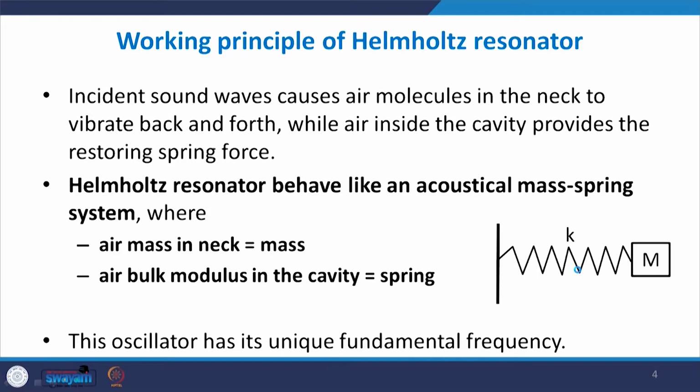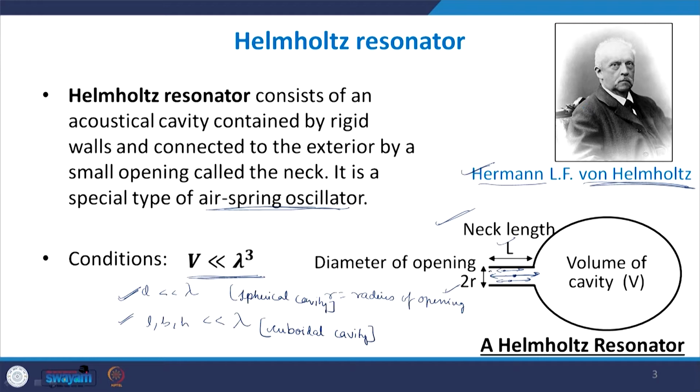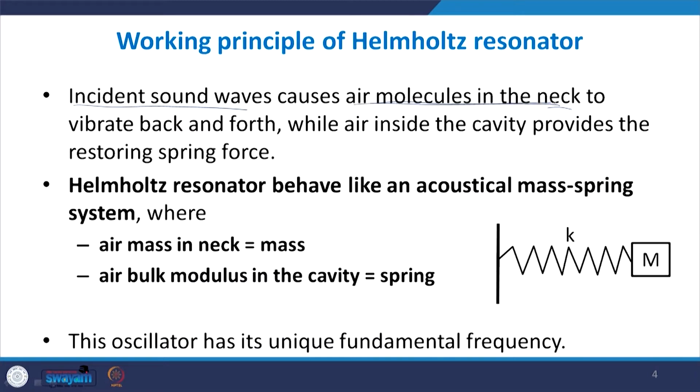So, the incident sound energy is driving these air molecules, and hence a heavy absorption will take place, lots of energy will be lost. That is what I have explained to you, that whatever the incident sound waves are, they will cause air molecules in the neck of the cavity to move. Here, the air molecules inside the neck of the cavity become the mass of the system. In the panel case, it was the mass of the panel. So, here the air molecules in the neck will start to oscillate back and forth when the acoustic coupling takes place. They constitute the mass, and the incident sound energy will be lost in driving this mass.